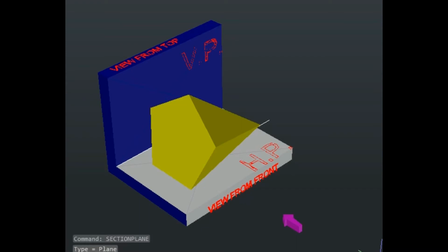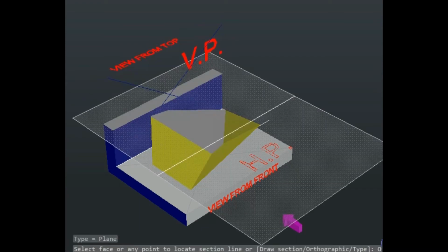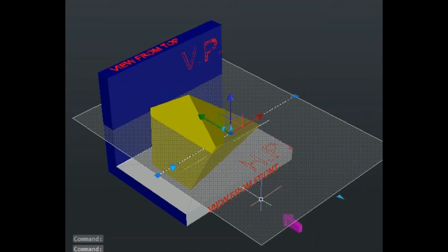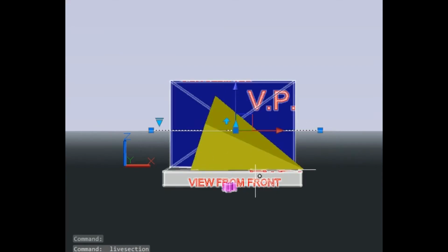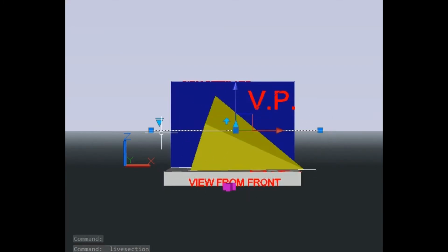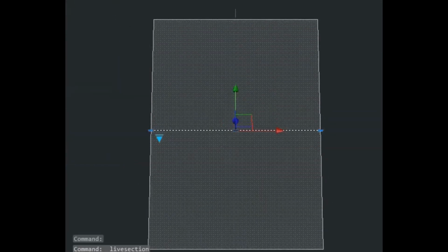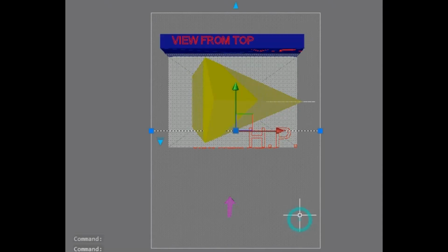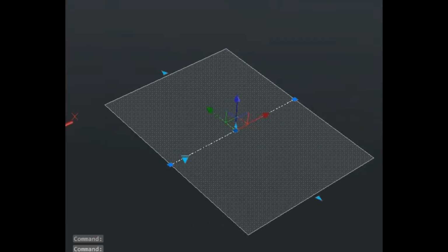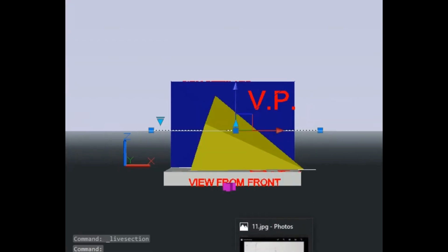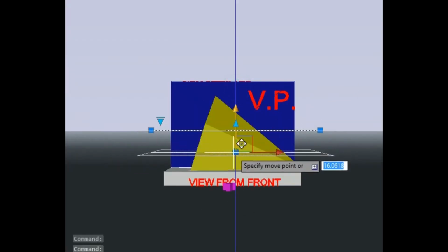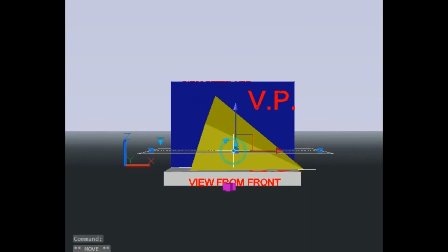So this is the final placement of the pentagonal pyramid on the HP. When you take the section plane parallel to HP, you will find something like this. Now I have taken this section plane which is parallel to HP. I'll just remove some portion. I have not taken the exact position, the section plane is 6 above HP. So now I will try to just make it lower because 6 is very less.